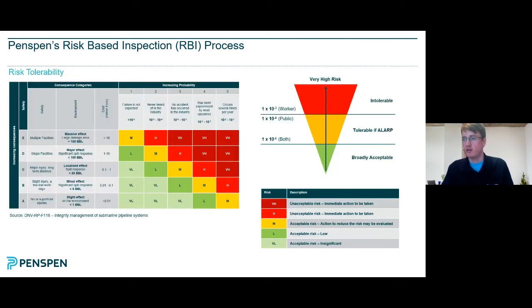So moving on. Again, there's published guidance on what is acceptable or tolerable probability of failure. On the right-hand side, there is the risk tolerability carrot. That's generated from HSE's document, Reducing Risks, Protecting People, or R2P2, and that gives us some orders of magnitude of failure probabilities that are considered to be tolerable, both from an individual point of view and a societal point of view. And then again, on the left-hand side, referring back to DNV RP F116, there's some more rules of thumb in terms of orders of magnitude of probabilities of failure. And we can use these to inform our tolerable risk level.